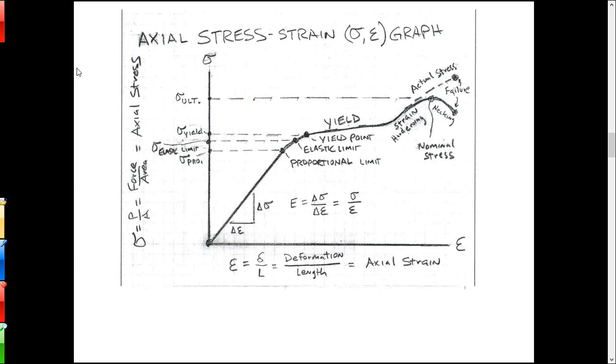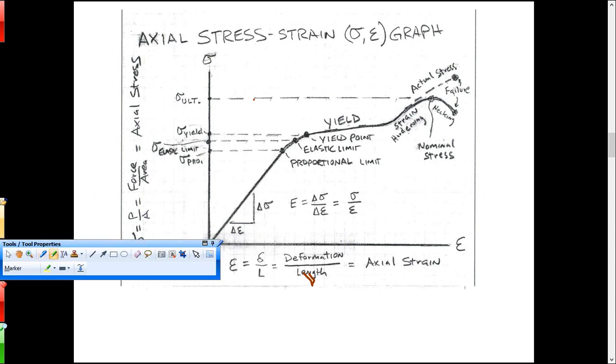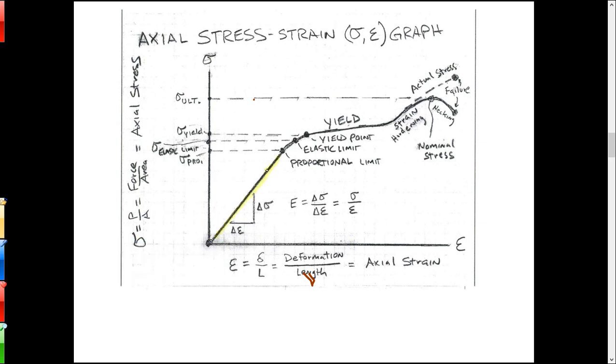Usually it's not quite as linear as I'm showing you here, but it is pretty much linear, and they also say generally an elastic portion of the graph. So the line goes straight up. As you pull harder on the material, it lengthens more, which really isn't rocket science, is there? But there's a directly proportional relationship.